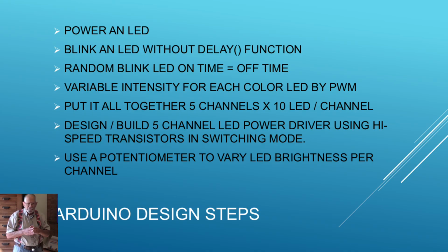Well, what's a method for doing this? I have an LED, and how may I change its brightness? Well, I can use a potentiometer maybe and vary that current around a little bit, more or less resistance, more or less current, right? Or I can use pulse width modulation.